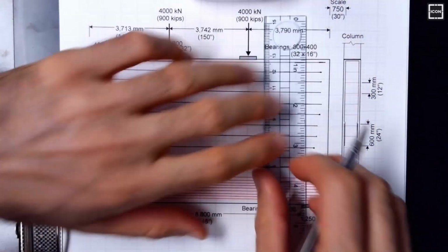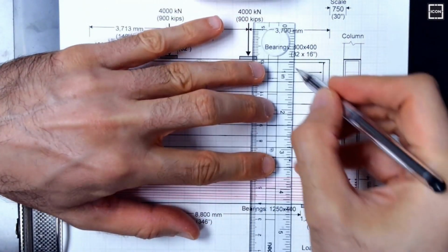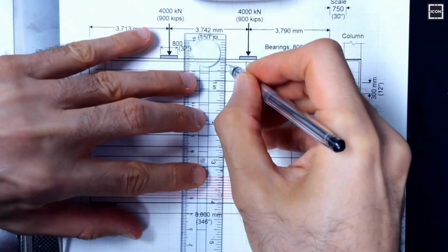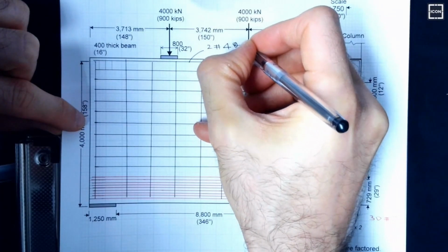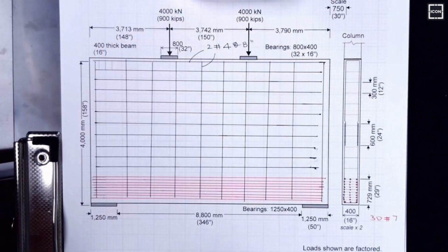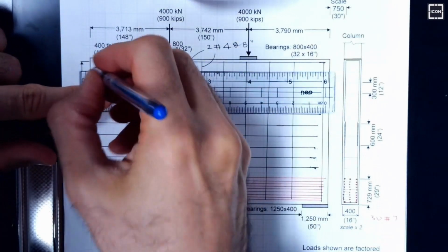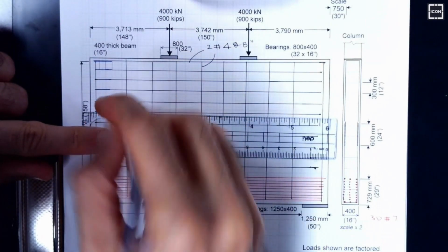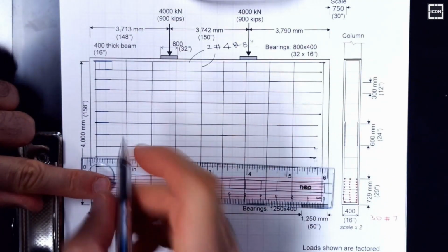Something like that. And of course, I'm not going to go super detailed with the vertical one, so I'm just going to show a couple of vertical crack control reinforcement. But the spacing is the same, vertical and horizontal, right? Number 4 at 8 inches, both vertical as well as horizontal. You can always put additional reinforcement, and for such narrow members we really like to put U-bars at the edges to prevent any splitting. Same spacing, but some U-bars at the edges to confine. This would be good for both serviceability as well as ultimate limit state.